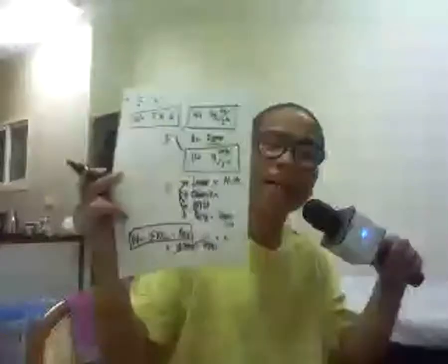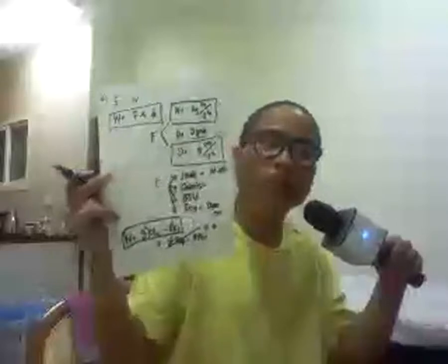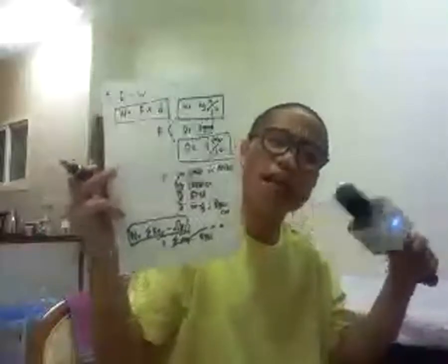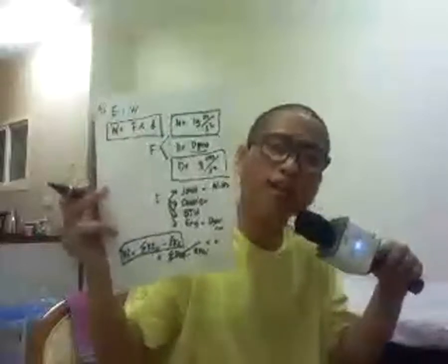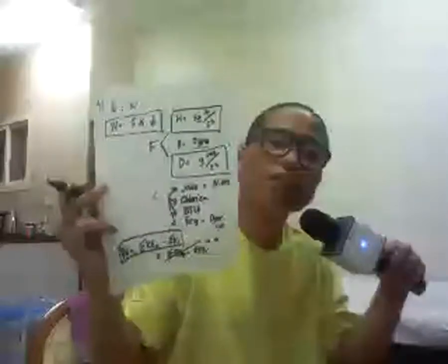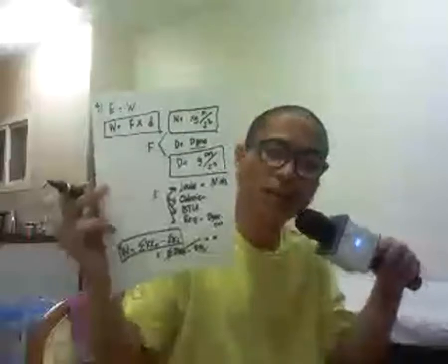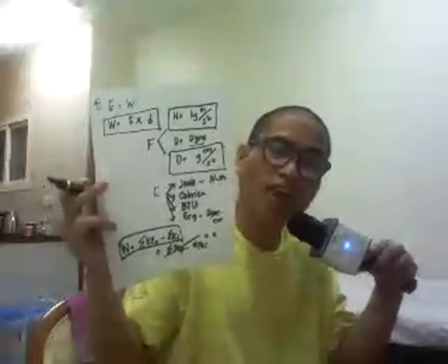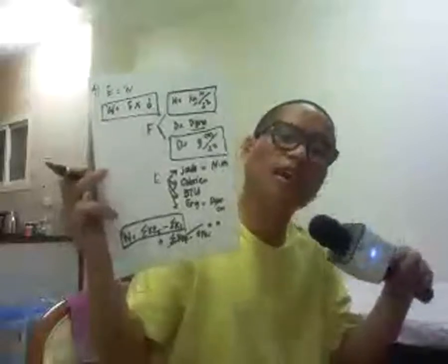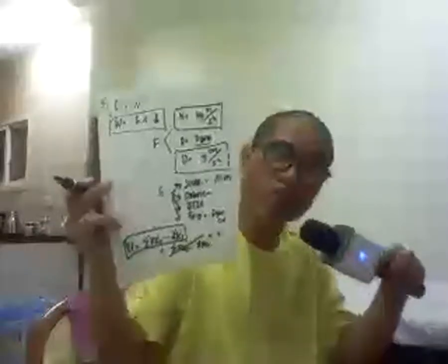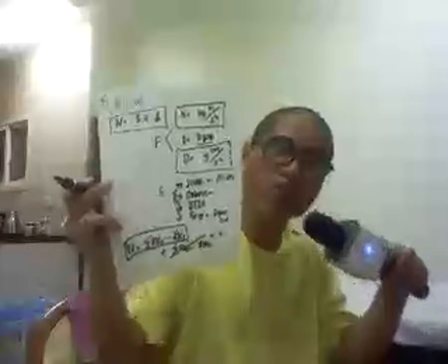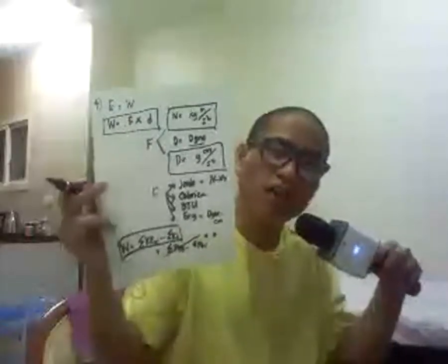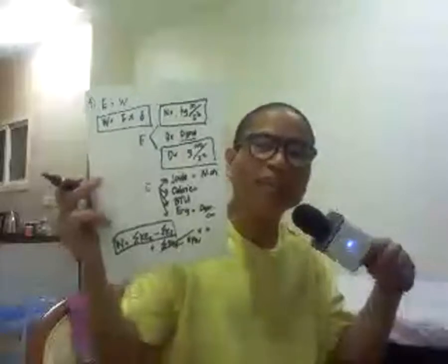Okay, that's analysis. Some problems also will never mention directly, but it has the same meaning with other formulas. For example, shear stress. Shear stress has the same unit with pressure. Remember that one. And then shear stress is also shear force over the surface area. And sometimes it could only be interpreted as pressure. It's also force over area. Now, if the problem will give shear stress, now you can answer already because you are used with the word pressure. Okay, that's the technique.